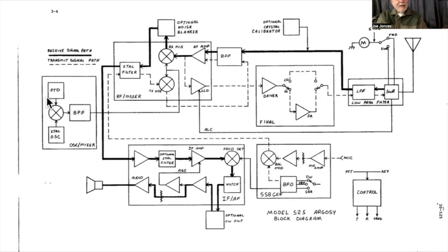And this is the, what is a PTO? I wrote it down on a piece of paper, I don't have the paper. I used to know what that was, but anyway, this is a variable oscillator. That's where you do your tuning frequency. You turn this, it changes the frequency. Here's a crystal oscillator. They mix and they come out to your band pass filter here for a specific band,